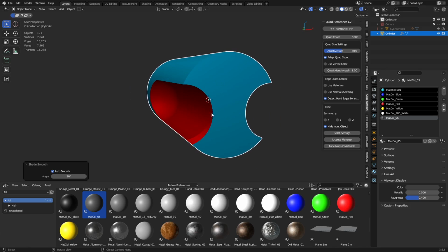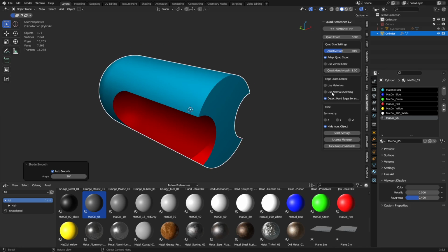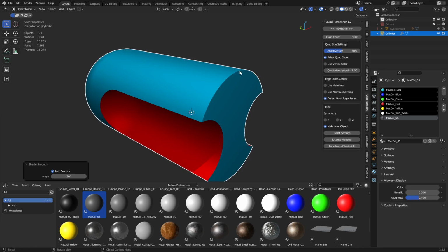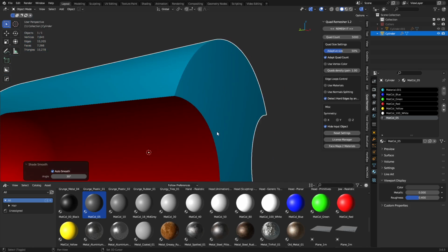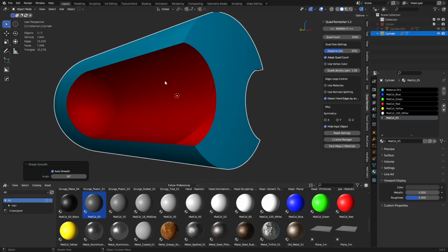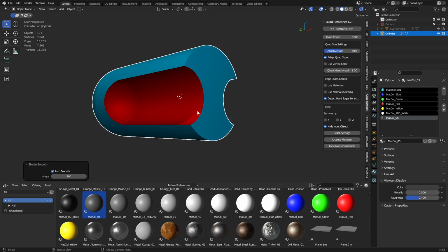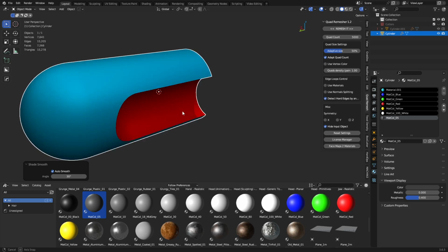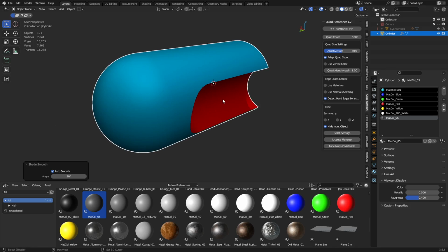One of the things that's kind of interesting is that when you use split normals, the normal splitting, you shade things auto smooth, these sharp edges like this, they're split normals usually. Watch my shading video if you don't fully understand that. But the thing is that certain times you want to split things, but you can't tag the edges sharp because it's a boolean, right? And it's not live, and so you'd have to collapse your mesh, and it causes a lot of problems.